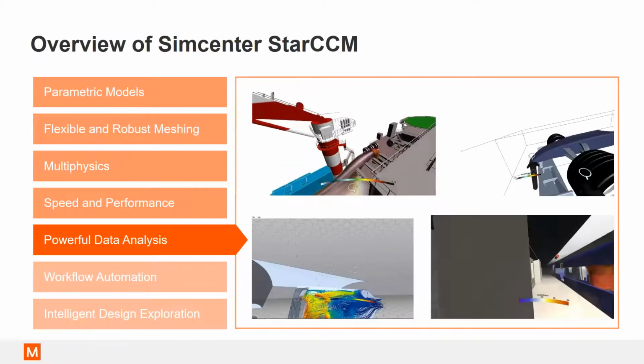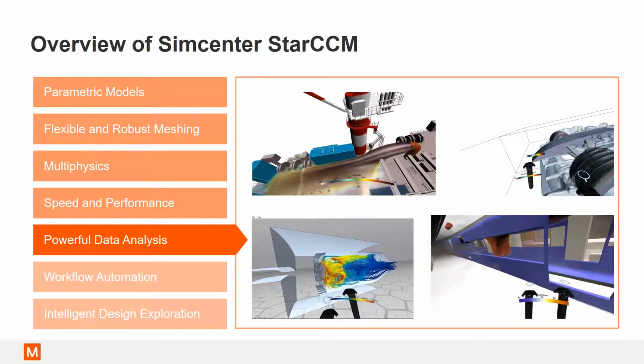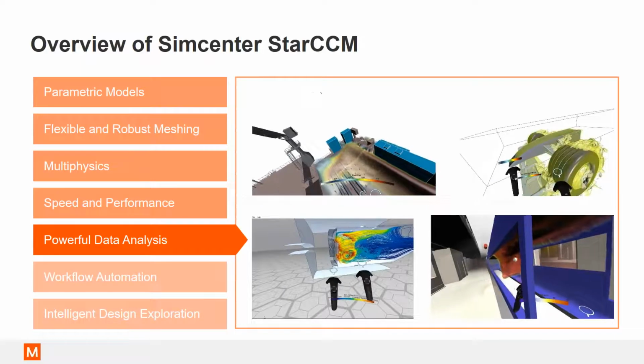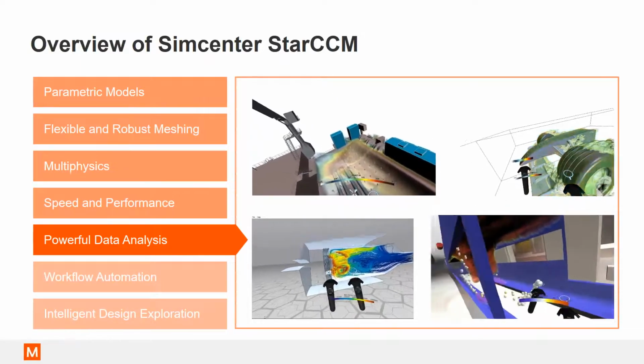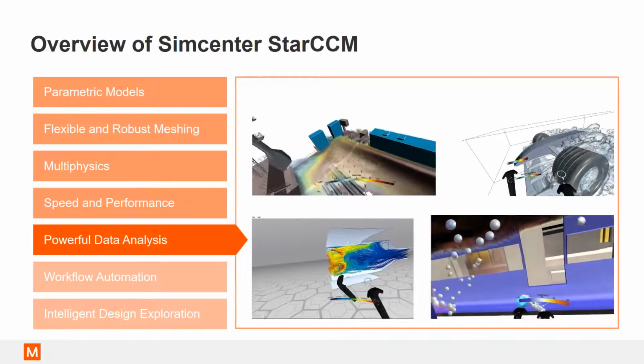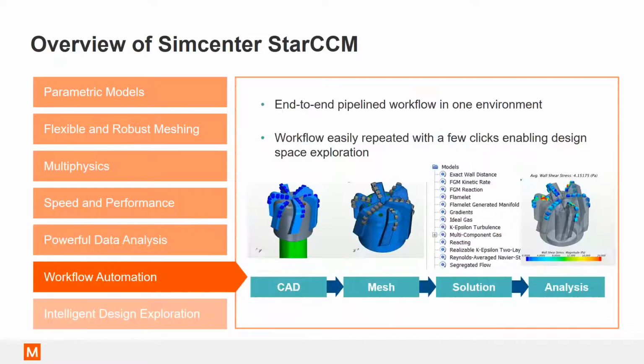Another cool feature is its virtual reality capability, where essentially you can use a VR headset to deep dive into the results. But one thing I did want to point out is the entire workflow within Star CCM Plus, from CAD all the way to mesh, running an analysis, are all connected in an end-to-end pipeline. So any changes in the CAD will be updated downstream. Now, this is available through the entire integrated process that is within every step of Star CCM Plus.